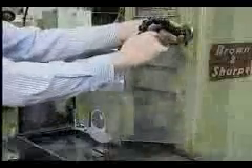Physical guards are the most preferred method of protection due to their simplicity and effectiveness. They can be permanent or adjustable and are usually made of metal, wire, or heavy plastic. Simply put, physical guards block the individual from coming in contact with hazardous parts of the machine.